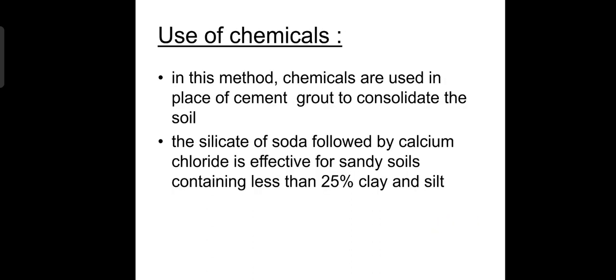Use of chemicals. In this method, the chemicals are used in place of cement grout to consolidate the soil. The silicate of soda followed by calcium chloride is effective for sandy soil containing less than 25% of clay and silt.